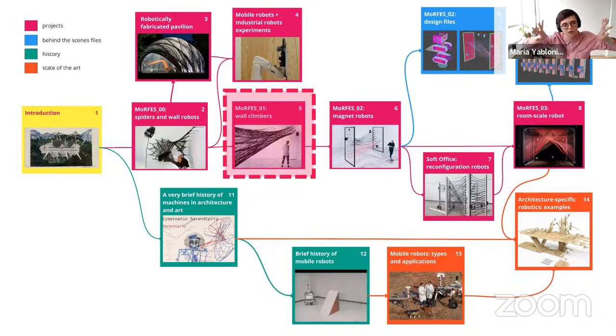Basically, what we did is we took those anchors, because the anchors are actually bolts with a custom designed hook attached to the bolt. And then after the fabrication process was done, we just screwed the bolts a little bit deeper into the wall so that the whole thing post-tensions itself.